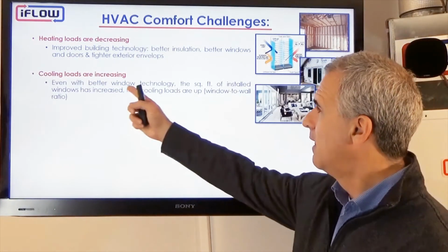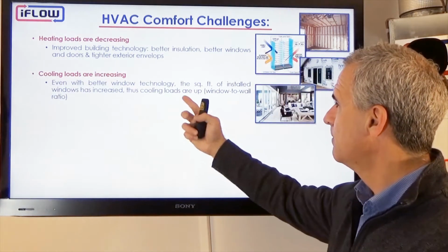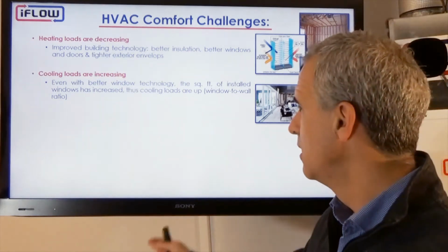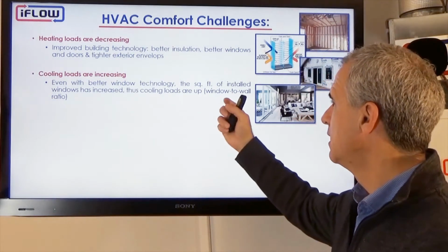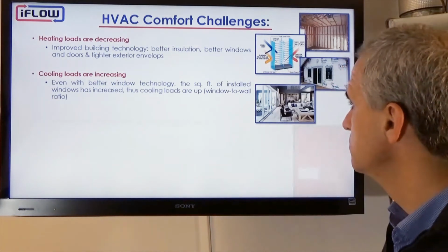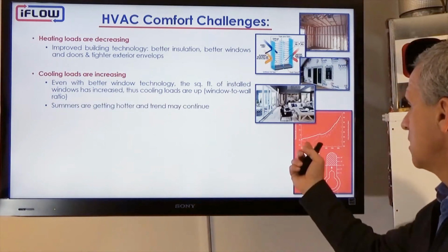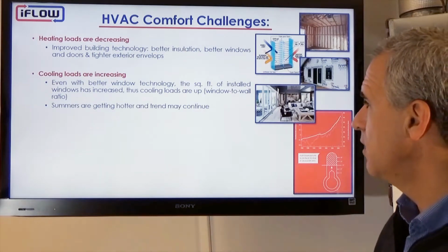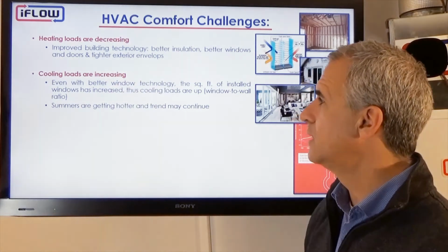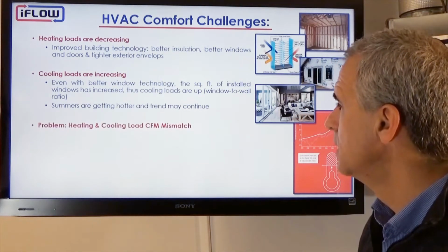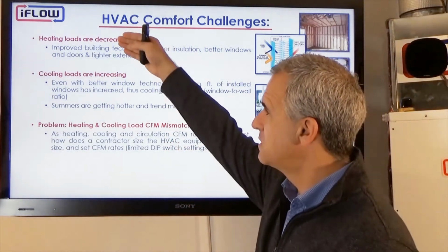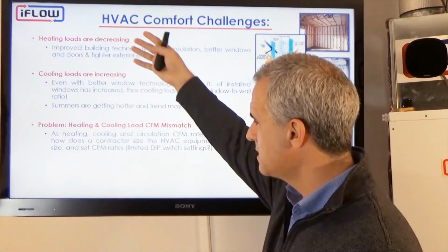So even though the window technology is getting better, the amount of square footage of windows that we're putting in is increased, so the window to wall ratio is up, and thus cooling loads are up. Summers are also seeming to be getting hotter, and that trend may continue, so the increase in cooling loads will continue. So the problem for HVAC equipment is that as the heating loads decrease and the cooling loads increase,